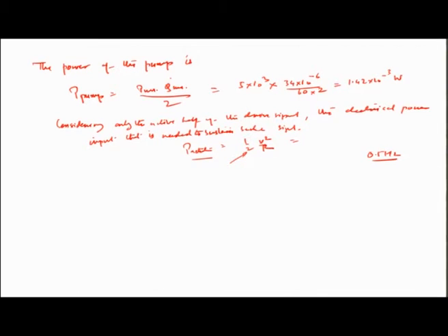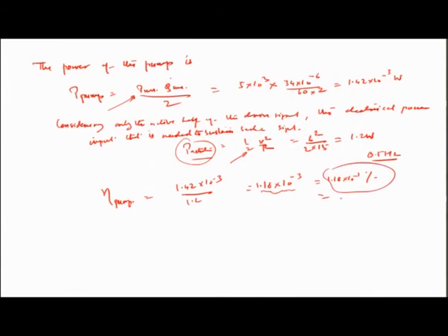So, when we talk about one such square signal which has been given, the total amount of power that is consumed here is 6 square by 30. So, that is 1.2 watts, and therefore, in this particular case, if such a signal has produced this kind of a back pressure or pumping power, then the efficiency of the thermopneumatic pump or actuator is actually equal to 1.42 into 10 to the power of minus 3 divided by 1.2, that is 1.18 into 10 to the power of minus 3, or even better in percentage, it is 0.118%. So, this is how the efficiency of a thermopneumatic pump is computed.